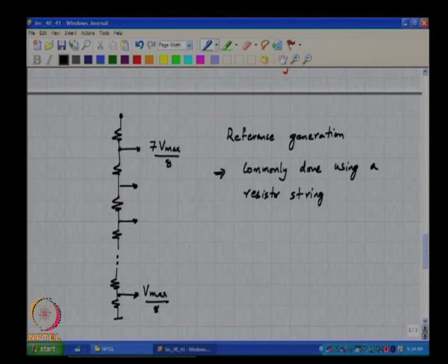So, if the resistors for instance vary across the die, and please note that the flash array is physically a big thing. So the resistor string has to go from one end of the array to the other. So if there is a gradient of resistance along the die, it means that these resistors are all not identical, and there is a gradient in these resistors, which will then boil down to DNL and INL in the converter, even if the comparators were ideal.